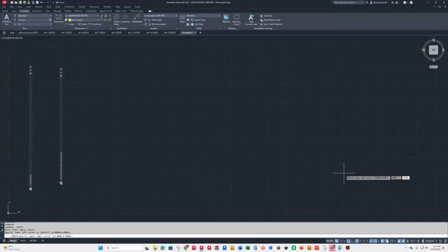And where did I pull that number out of? Well, you don't want to know. I just pulled it out of nowhere. It's a magic number. Why? Because it's big enough. Because you got 450 plus 250. Well, that's 700. Well, 1,000's definitely bigger than 700, and that'll give you plenty of room. So that's what we're going to do, and it works for me. Now, don't forget, you got to zoom all or zoom extents, and now you're ready to draw.